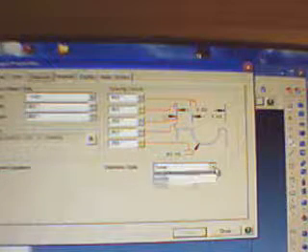Right now you're in what is probably smart mode. So we want to go to the file up in the top left hand corner, come down to properties. In the general tab area we want to move to the dimensions. Right here in this area it says smart in this white area. We're going to go down, click linear, apply, close. Now we can grab this dimension and pull it in the center and up. That's what I'm doing here.